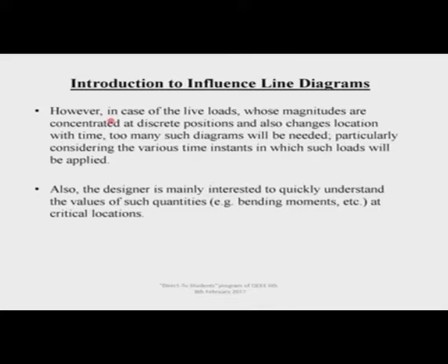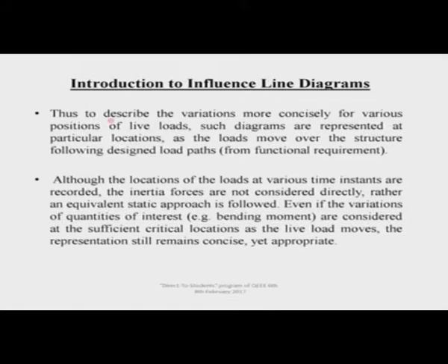It is mentally, to some extent, a barrier to accept the time variation. In case of live loads, whose magnitudes are concentrated at discrete positions and also change location with time, too many such diagrams will be needed to express the variation, particularly considering the various time instants at which such loads will be applied. And the designer's main interest is to know the variations at critical locations. So he is exploring what the variation is in different places, but if the structural form is known to him, he may actually know where these variations become critical, and he will be interested to see the variation of the live load there.